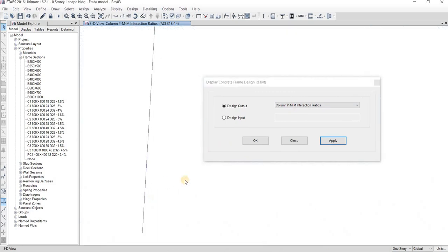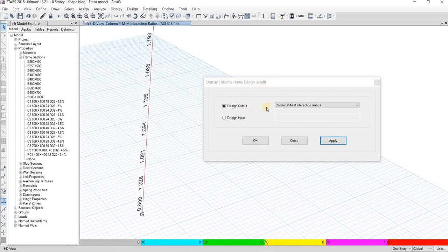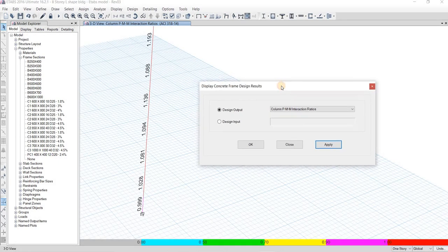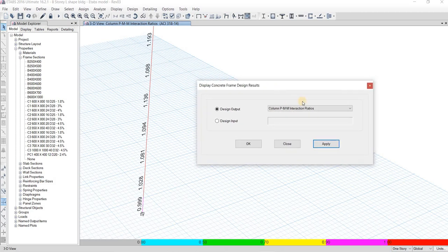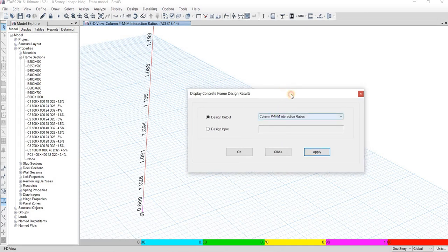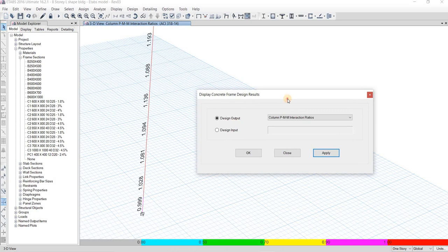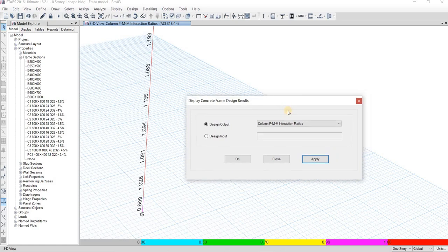So in this case, for projects like this, and this is 7,000 psi, some designers or contractors require self-consolidating concrete. So there is no slump test, there is a spread test to do, to make sure of the quality of the construction.